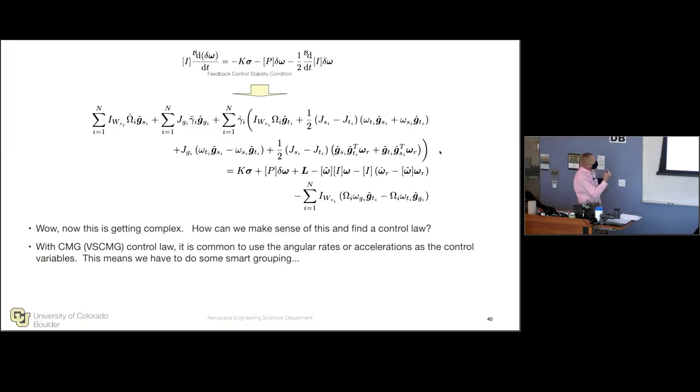So before we just had the wheel accelerations and thus the motor torque, if you put it in the motor torque form, to figure out how we generate the right-hand side. Now we have wheel accelerations, we have gimbal accelerations and gimbal rates. Now of course gimbal acceleration and gimbal rates you cannot individually prescribe. That doesn't make sense. Don't accelerate but keep going faster. It doesn't work. So we'll have to pick one of them.